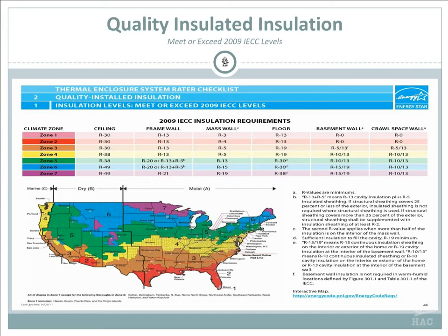Again, it talks about insulation. These are your walls. These are your minimum R values in order to meet 2009 IECC levels. So if you're going to Energy Star, I talked about that a little bit. With Energy Star in Zone 1, you're probably looking at an R38. Framed walls, you're looking at an R13, but you're also going to be putting a foam board on the outside, and we'll talk about that in just a little bit. Again, these are your minimum levels depending on what zone you're in.